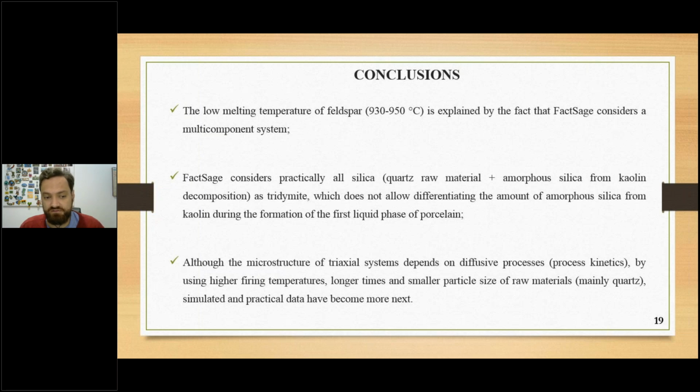Although the microstructure of triaxial systems depends on diffusive process kinetics, by using higher firing temperatures, longer times, and smaller particle size of raw materials, mainly quartz, simulated and practical data become more aligned.